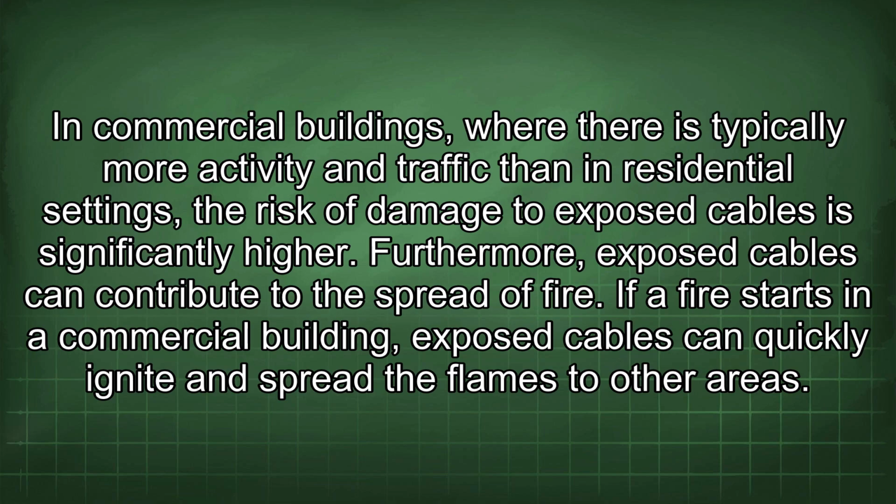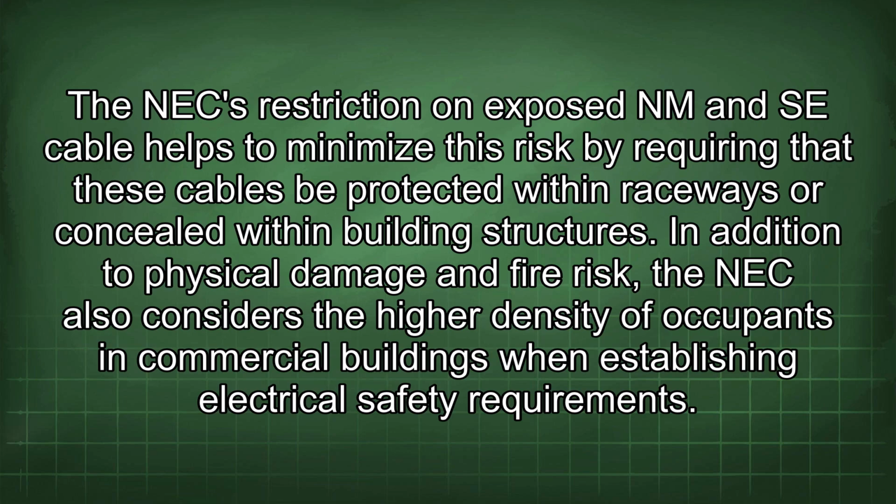Furthermore, exposed cables can contribute to the spread of fire. If a fire starts in a commercial building, exposed cables can quickly ignite and spread the flames to other areas. The NEC restriction on exposed NM and SE cable helps to minimize this risk by requiring that these cables be protected within raceways or concealed within building structures.